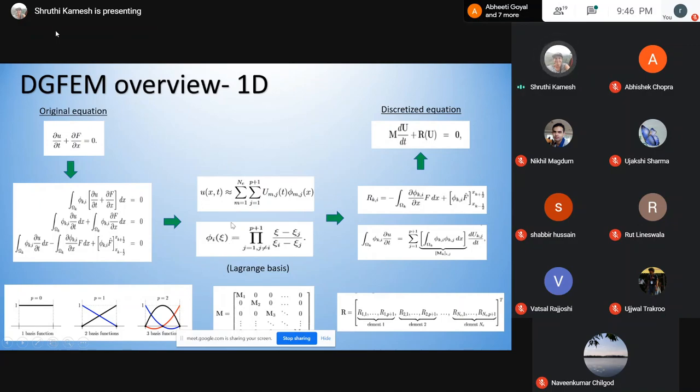And the Galerkin formulation says that I use the same basis functions for my solution. So you approximate your solution u, which is what you're solving for over here, as a combination of coefficients and basis function values, right? These are called basis coefficients over there. So what this entire term means is that for each element m, my solution is made up of this combination of values across different nodes.